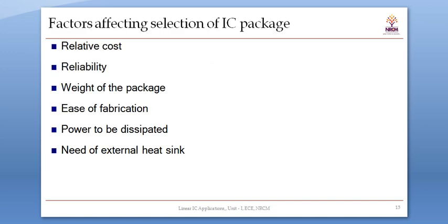IC package. So these are a few factors which affect the selection of IC package: relative cost, reliability, weight of the package, ease of fabrication, power to be dissipated, and need of external heat sink. So these are the factors which affect the selection of IC package.